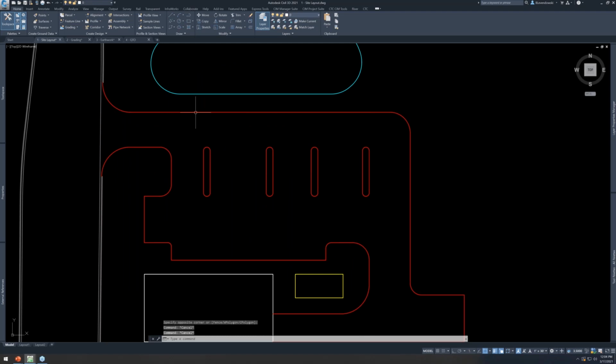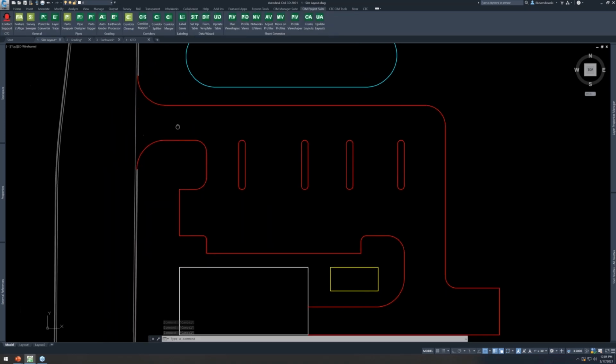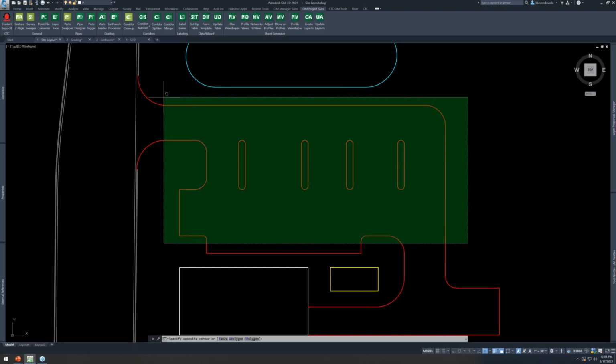And what we're often doing is running offsets on all this stuff. And as that geometry changes, we have to update those offset lines and so forth. So I wanted to plug in one of our tools right here so you can see how even in just 2D layout, some of these tools can really help. So we're going to take advantage of AutoGrader. We're not going to get into the grading portion quite yet, but we just want to take advantage of automatic offsetting. So all of these are polylines.